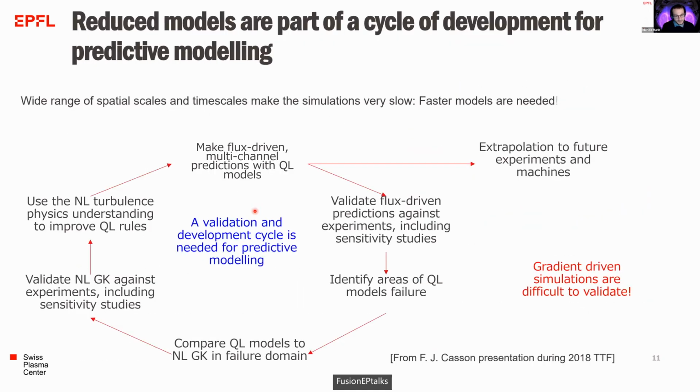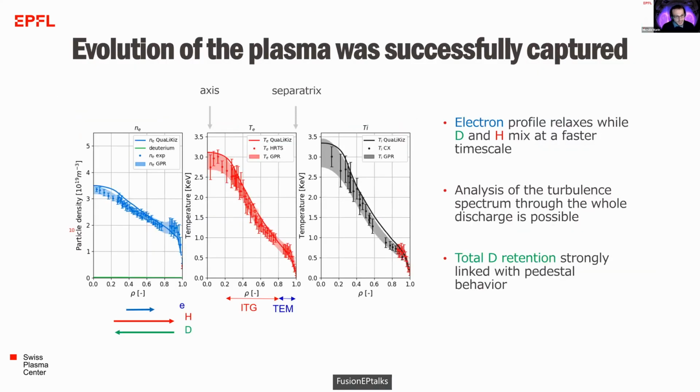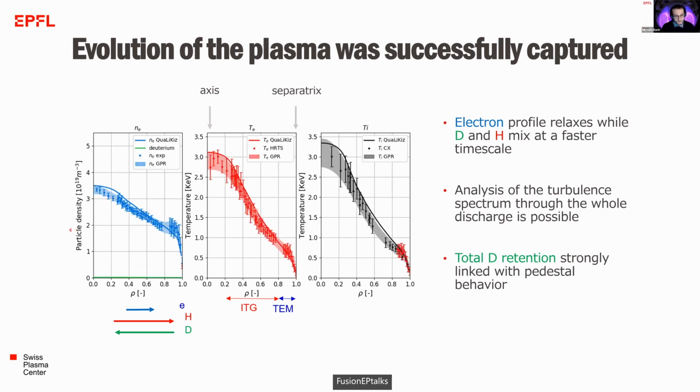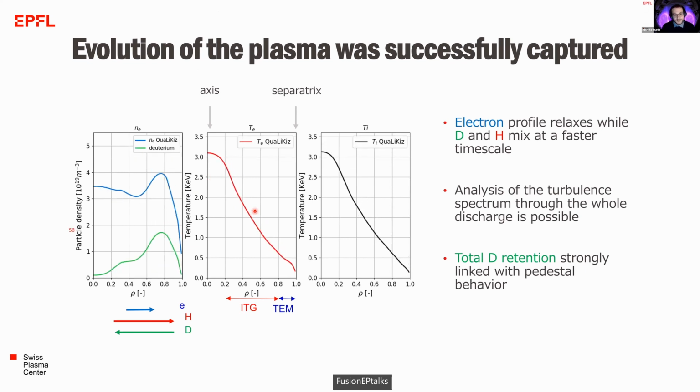For example, when there are strong transients, as was the case during the pellet experiments, the time step went down a lot, up to 1e-7, so microseconds. That's not really physical but there for numerical reasons, and it can slow down the simulation considerably. This is what works for JET. The exact grid parameters for other machines are a little bit of trial and error.